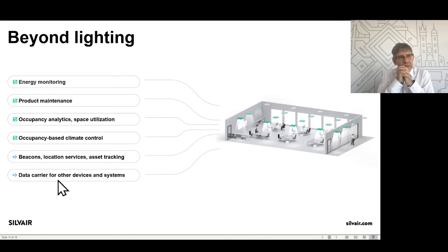And then, of course, the question is, how do you collect that information from fire extinguishers located across the building? And of course, if your lighting system is based on Bluetooth, those Bluetooth luminaires can receive signals from sensors embedded in fire extinguishers and then provide the data to the monitoring application that monitors the fire subsystem. So this is yet another example of how those systems can interoperate together as long as they are based on the common standard.